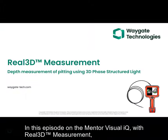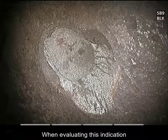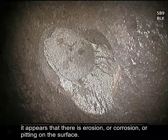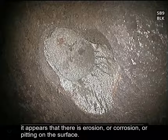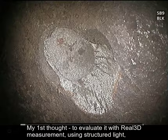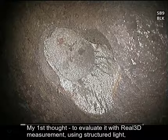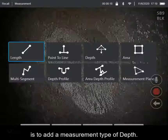In this episode on the Mentor Visual IQ with Real3D measurement, I will be discussing depth measurement of pitting using 3D phase structured light. When evaluating this indication, it appears that there is erosion or corrosion or pitting on the surface. My first thought to evaluate it with Real3D measurement using structured light is to add a measurement type of